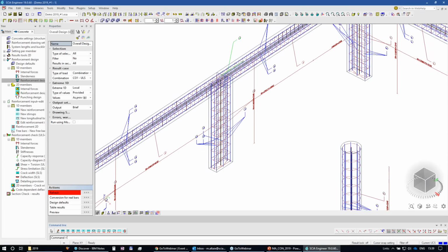And then we are using a kind of factor to redistribute those reinforcement to the width of that edge, while the check itself uses the real location of those bars. And somehow this is more precise, in fact, because we know exactly where the location of the bar is, then we can exactly calculate the effective d, or the distance from the center of the bar to the neutral axis for the calculation of the resistance.